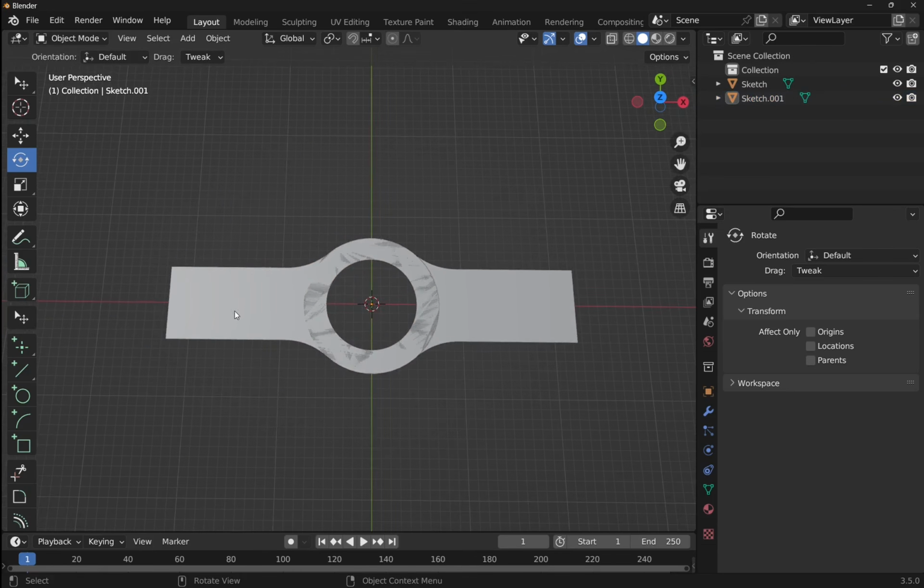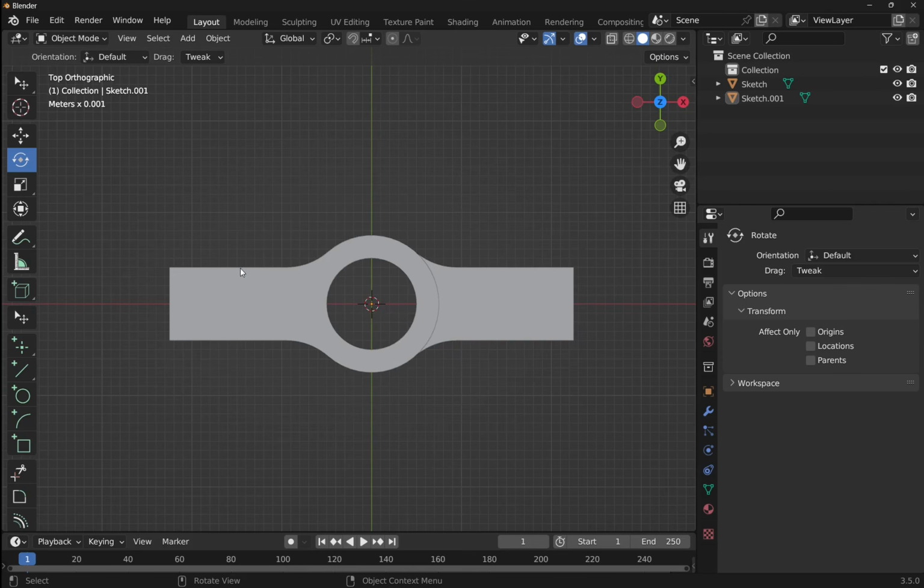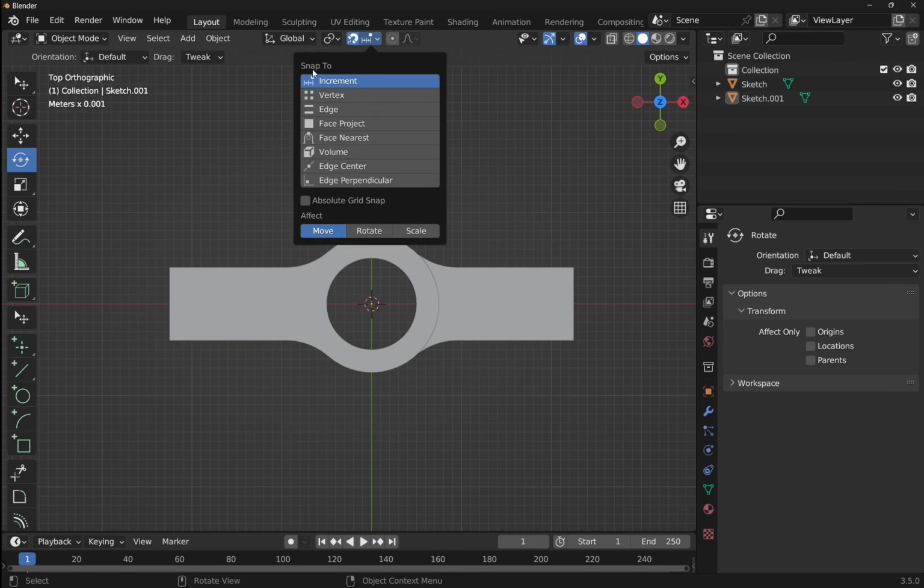Now what I want to do is click on the Z axis and move this and snap this edge to this edge. To do that, we're going to use the snapping tool. If I look to the top, we can see this curve here, which is actually a magnet. So I click on the magnet, we're in snap mode now. To the right hand side, we've got this gauge. If I drop this down, we can select the snapping options.